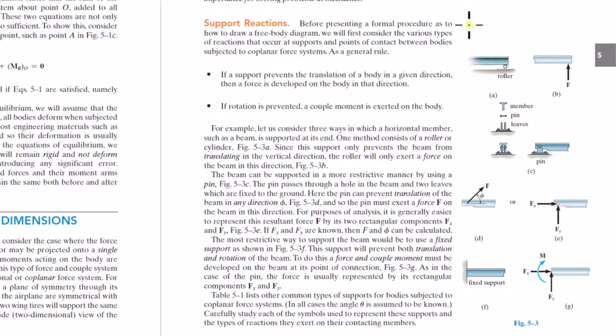And we talked about, in a previous video, how body forces, like gravity, for example, act equally in the same magnitude and direction on all particles of the body. It's a safe assumption, so you can put that body force at the center of gravity, or like a centroid type position. It might be the actual geometrical center of the body, unless the mass is not uniform, then it'll be the center of mass instead of the actual centroid position of the body.